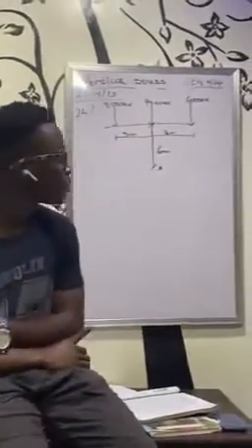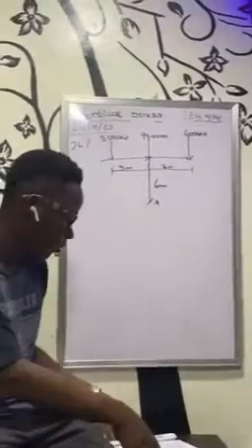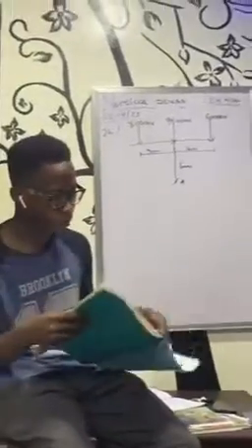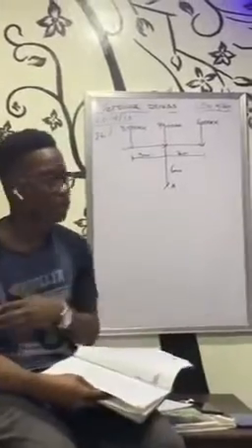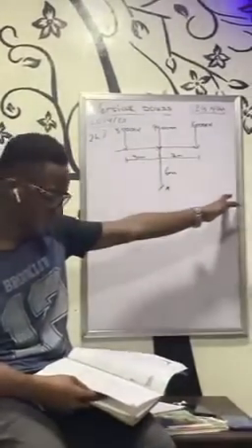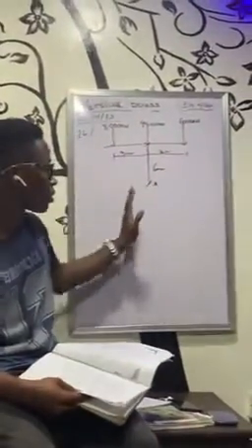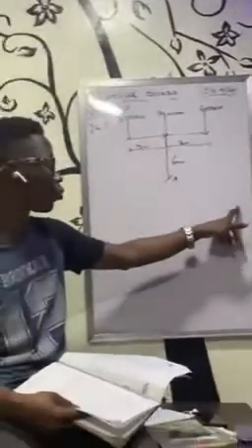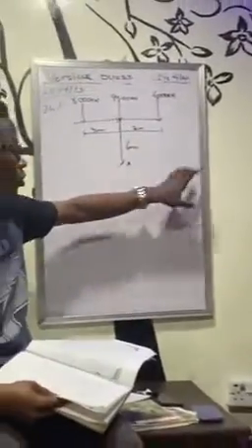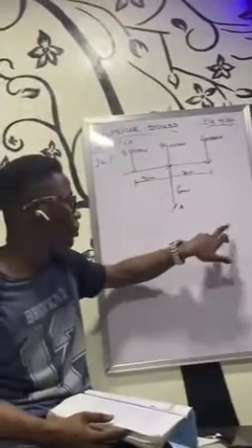So in terms of 2018, for the first part, we solved a question on vertical stresses where we had 2 point loads, and we're taking our vertical stress to a point. We found our radial distance r to be the perpendicular distance between the forces and that point. We had our depth z to be the depth between the ground level and the point we are taking vertical stress to.